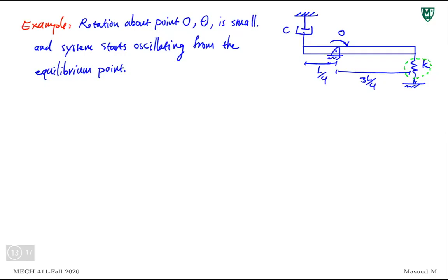If you start from equilibrium position, the initial stretch or compression in the spring takes care of the effect of weight, and we don't have to worry about it. If it doesn't start from equilibrium, it's a different story. Like the spring mass system, we would have to take into account how much the spring is stretched or compressed because of the initial effect of weight.